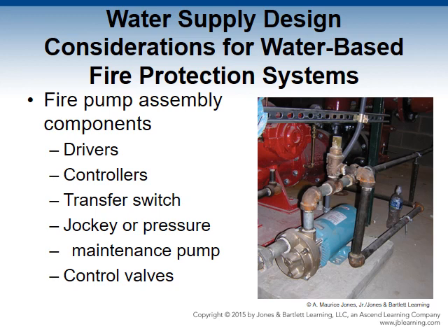Many use electronic and microprocessor-based technology to control, monitor, and store information. This results in less dependency on mechanical components that are more prone to fail. Typically, they have a runtime so that even if the system pressure stabilizes, the pump will continue to run for a predetermined amount of time, unless manually stopped. They are configured differently depending on the type of the drive motor, and they may be full service or limited service.